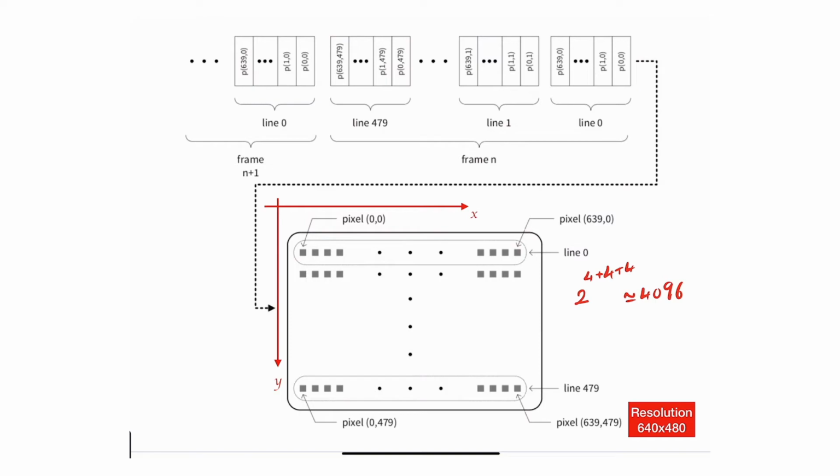And in order for you to maintain the values of the pixels on the screen, so that our eyes can actually see it without flickering, you need to refresh that screen or that frame at 60 hertz basically. Which means that this particular frame has to be refreshed every 1/60 seconds. So every second you're actually sending this 60 times. You're refreshing it 60 times. And the pixel data again are sent serially.